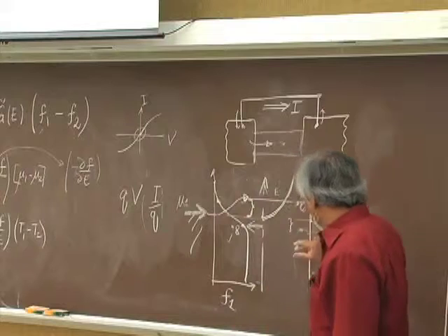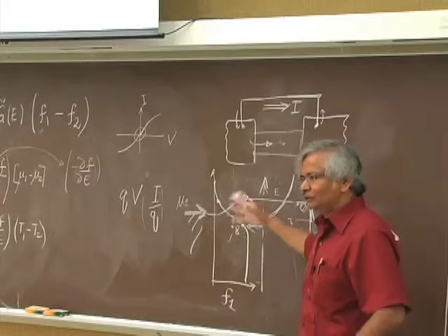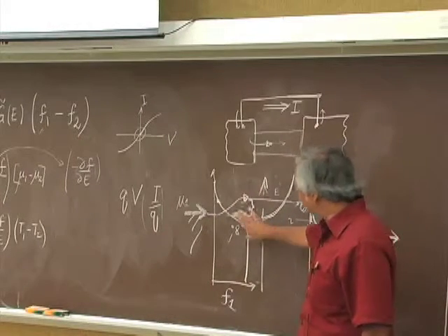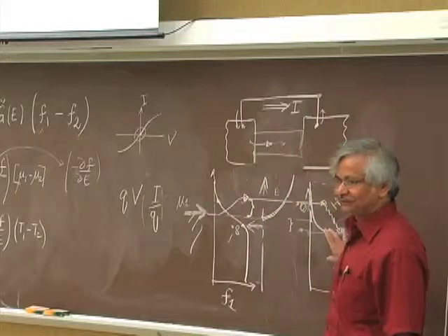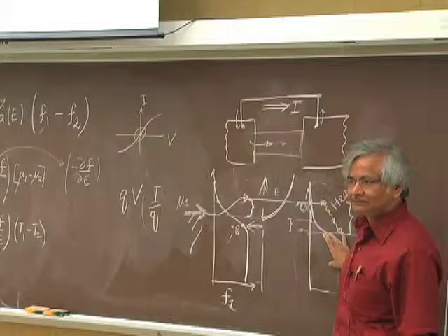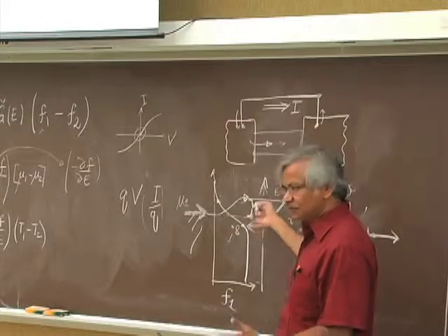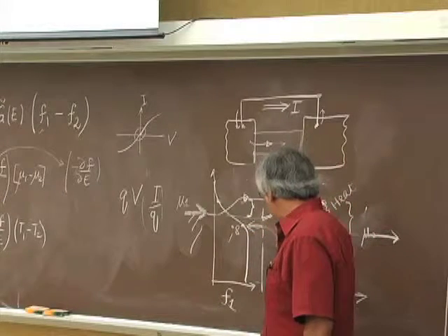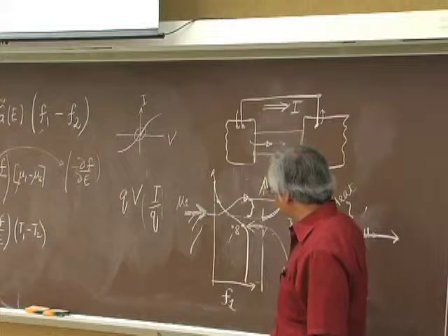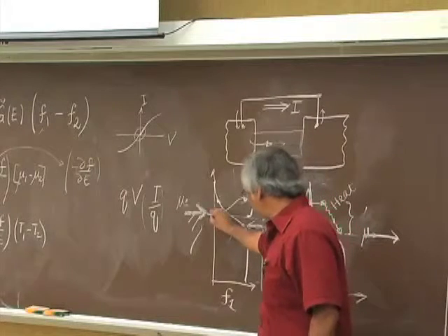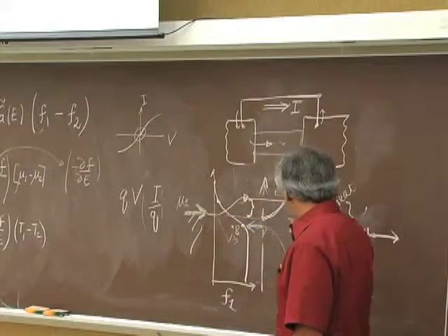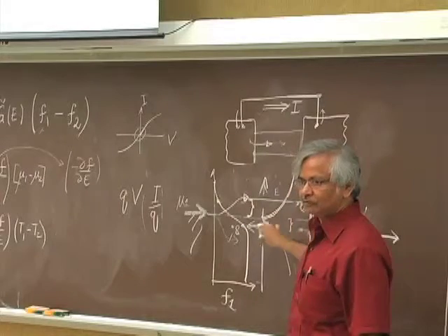But if you look carefully, what you find is it's not heating everywhere. This end is getting cooled and that end is getting heated. Now, of course, you'd have just the reverse if it was a p-type conductor. If all your density of states was down here, then you'd kind of first be going down and then be going up. It would have reversed.